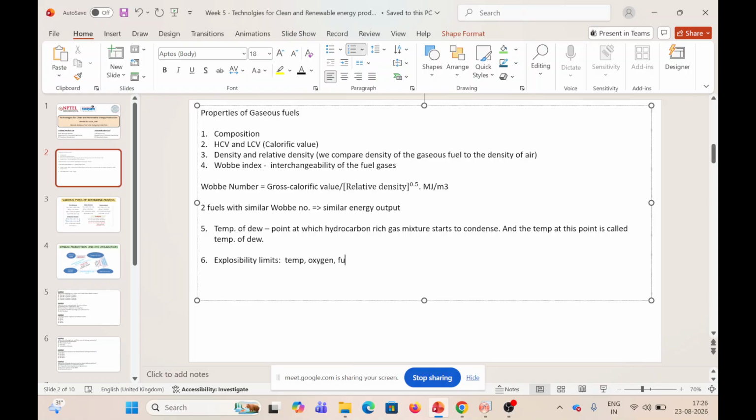It's going to be a fuel. I mean, there should be a source, right, for the burning. So that source, that is the fuel. Apart from this, for the ignition to start, there are also three things that will be required: one is the time, temperature, and turbulence.